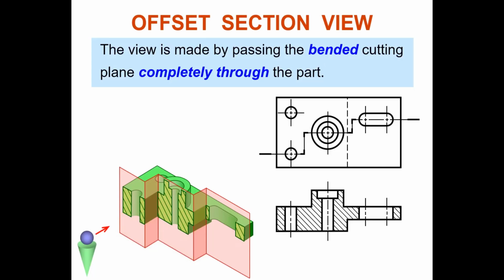Even if at the back there are certain features that would be hidden lines, even though we already cut and made section lines here, do not show hidden lines. We only see the section, so that you can easily facilitate your dimensioning. It is easy to represent and clear to understand what the internal part is.